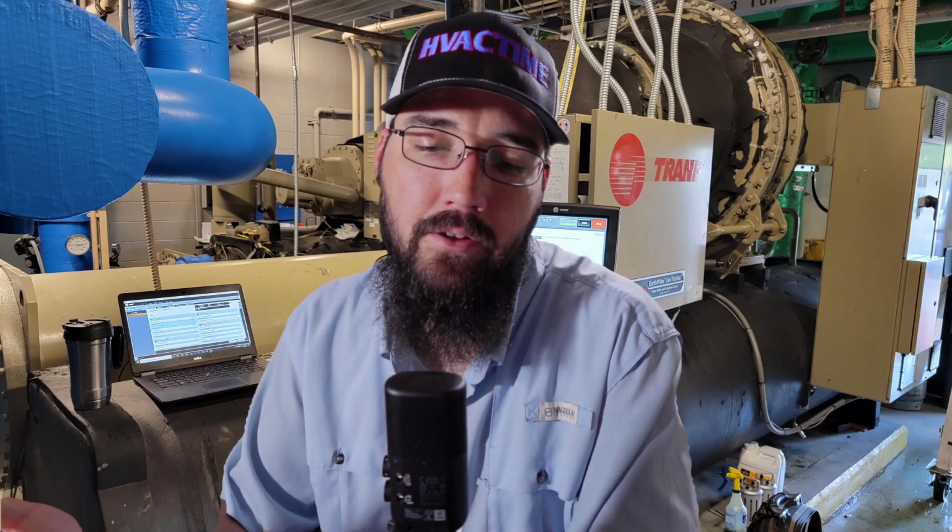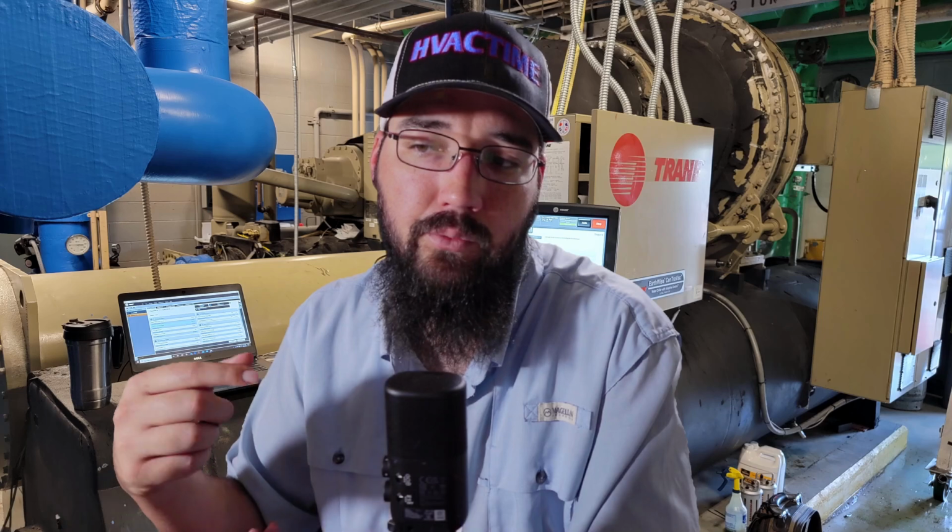then the next time it went to start, it would trip on oil loss, and the little peep sight sensor in the reservoir would show that we lost oil. So in a situation like that, the way we were able to correct it, well, one, the valve needed to be replaced, but two, to get it back online, the simplest option was we would usually put about 1 to 2 gallons into the reservoir. That was enough to allow it to start up and get online and start to circulate again.